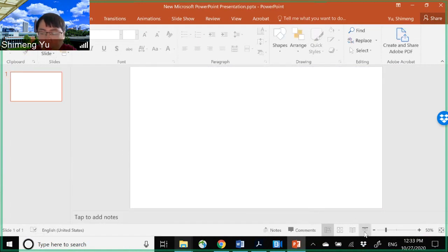So in the first midterm, we talked about the MOS cap, and we showed the band diagram along the gate to the channel direction. But in the second midterm, we focus more on the source to channel direction. So we have this band diagram. If this is the source, this is the drain, this is the gate, we are looking from the source to the drain. And then we have the PN junctions, because the source is n-type. So this is for NMOS.